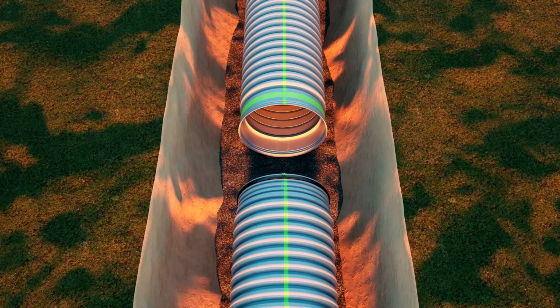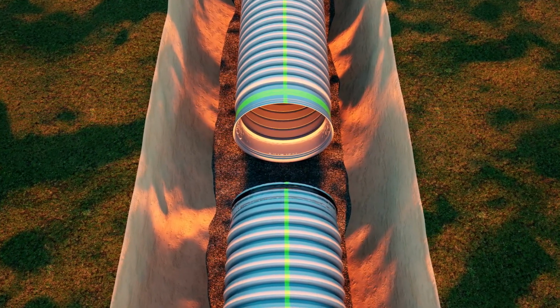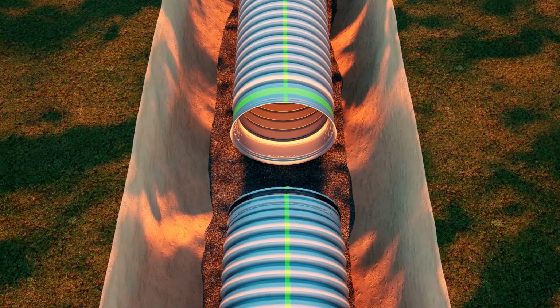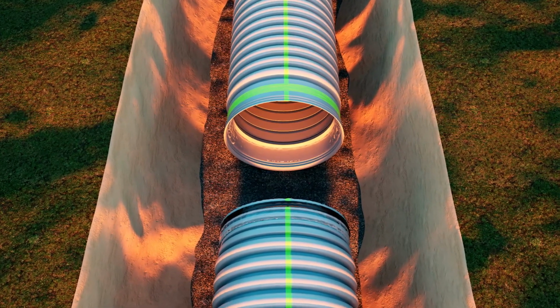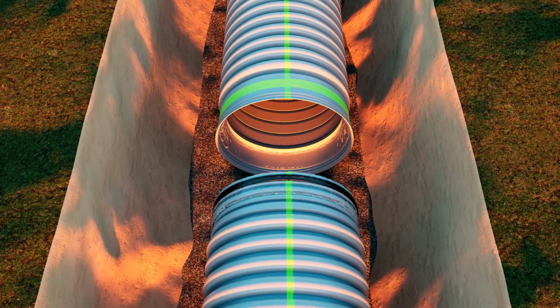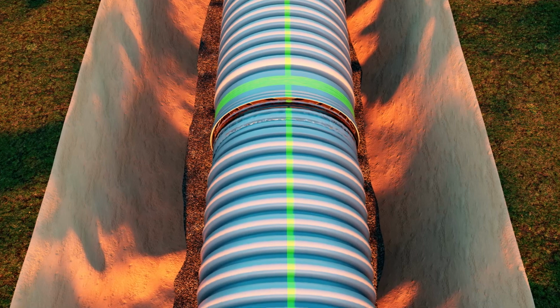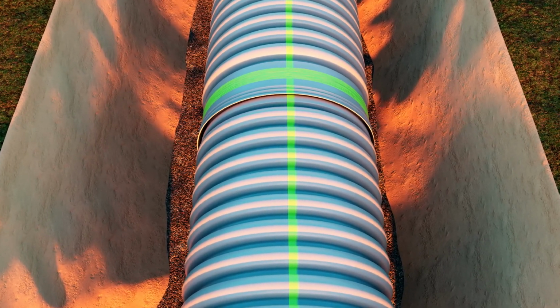Using a brush or applicator, place the pipe lube on the inside of the bell and around the gasket on the spigot end. Once the bell and spigot has been cleared of debris and the pipe lube is applied, the pipe can now be pushed home on line and grade. Once the home marker has been covered, the pipe has been fully homed.